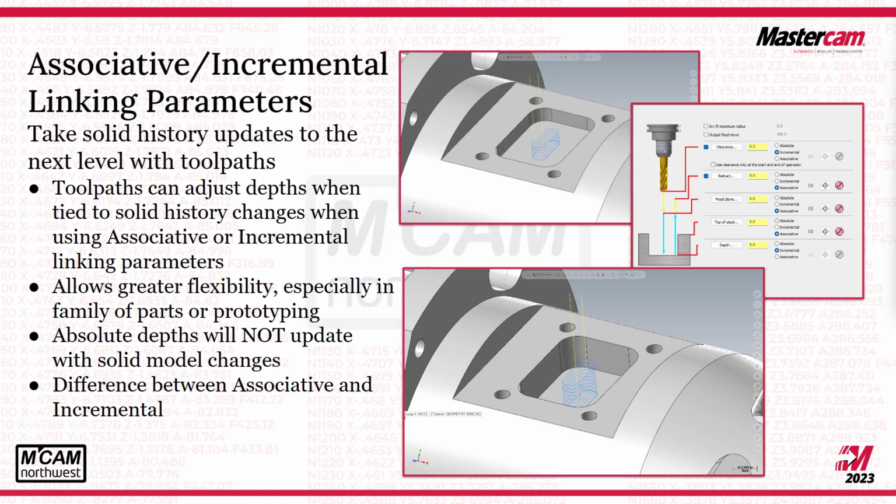The trick here is to make sure that we're using the correct linking parameters. We have to make sure that we are using associative or incremental linking parameters so that it can follow that Solid Edge. This will allow you a lot of flexibility compared to absolute, because when you program something to absolute, it will only program to that value relative to your WCS, right? Whereas when we are doing it this way with incremental or associative, it will actually follow the features.